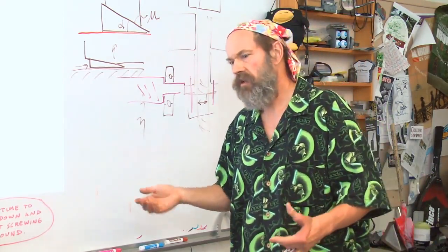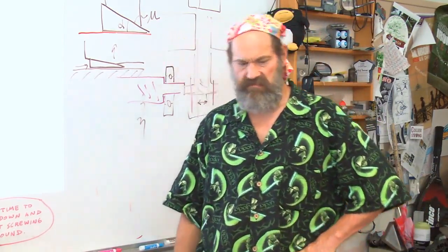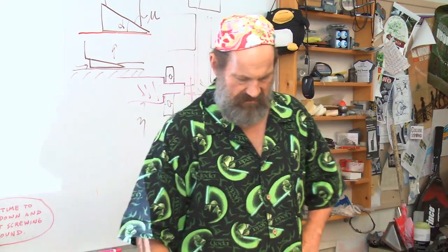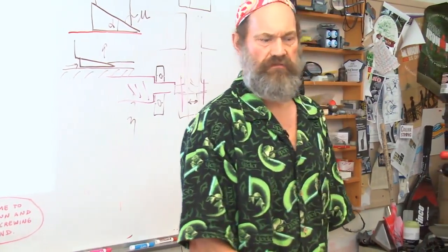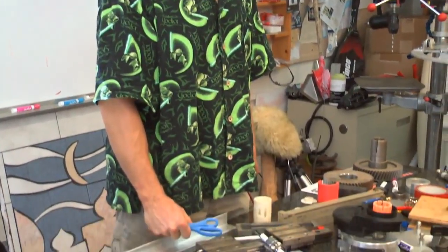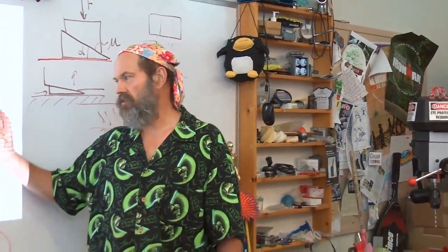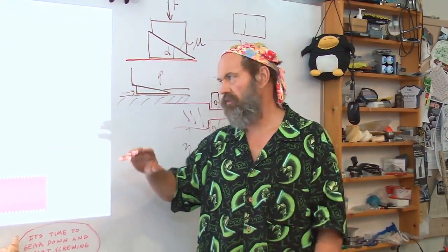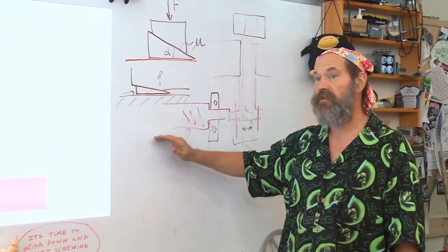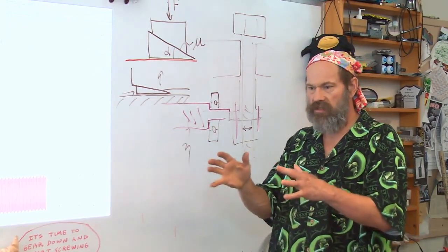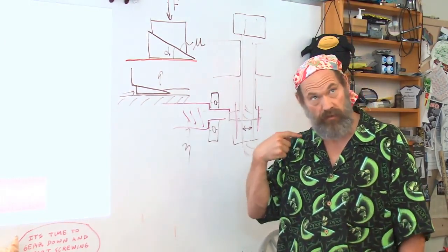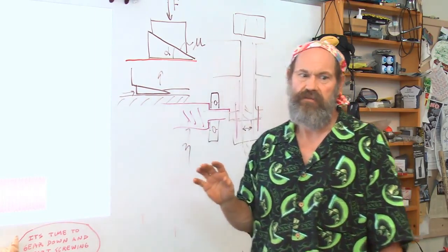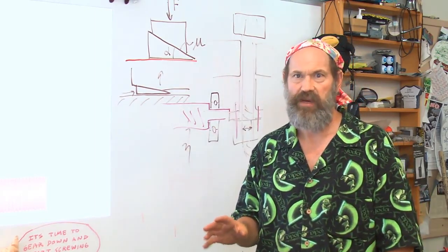Cheaper, cheaper, cheaper. Well, you have to remember that a guy like me comes up to work on the plate. I'm working on my machine. I put my wrench on it and bang! Break off. Bolt wasn't big enough. No wonder it broke. Stupid engineers. So it's not just that you're designing the stress in the bolt for the function of move fast or raise a load. Always remember the function requirement on your machines: human tolerant, because humans can be very, very rough on machines. My students know that. If the hardware can survive Alex coming in and playing with it, then it's probably okay.